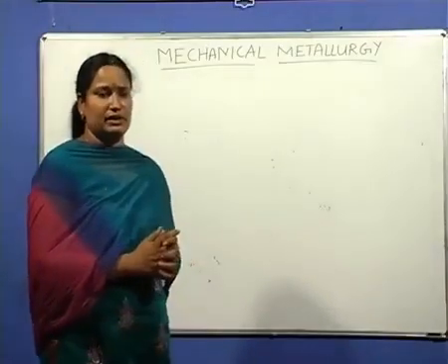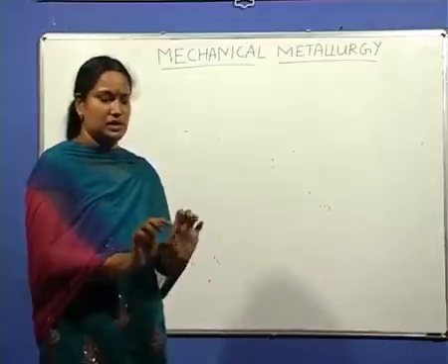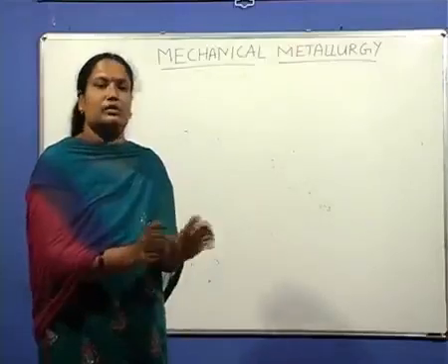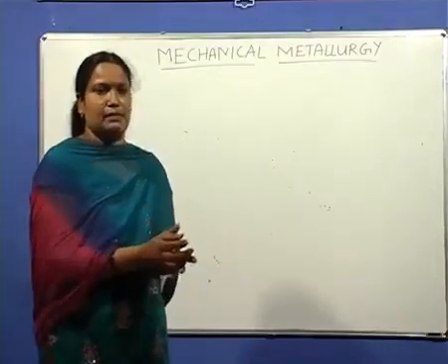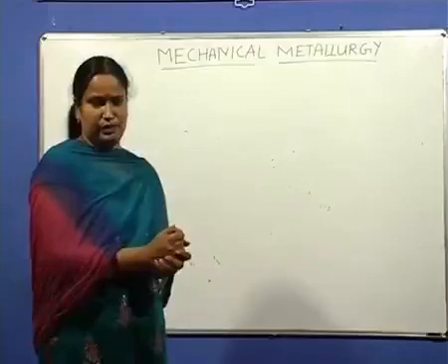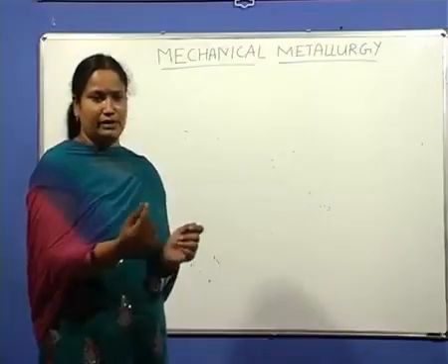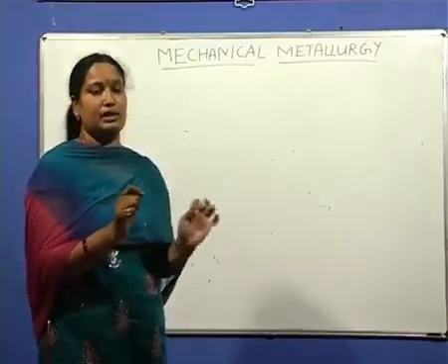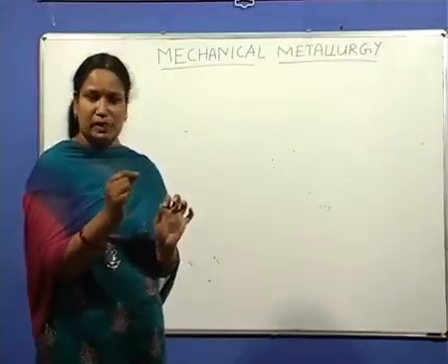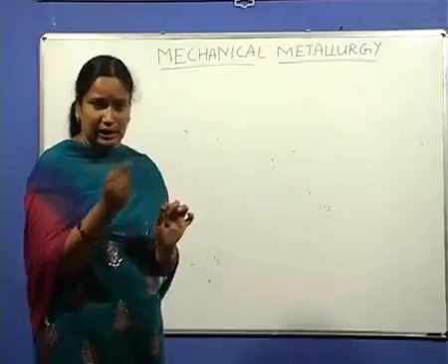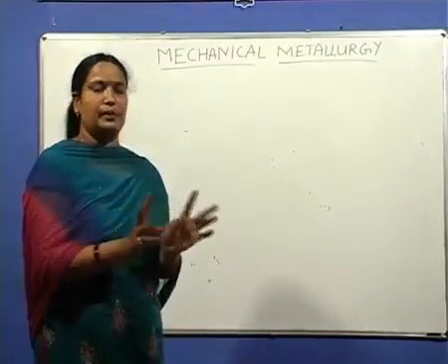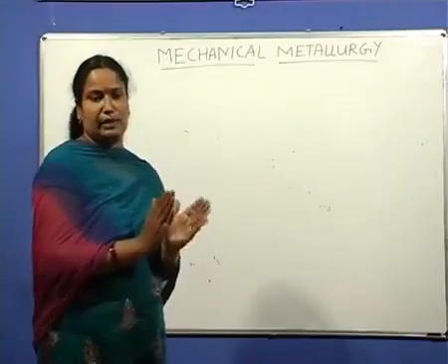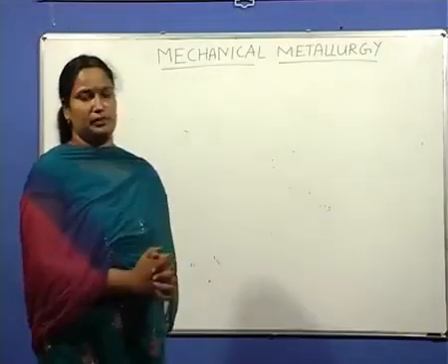An example of a brittle material is a chalk piece. When you apply some stress or force on a chalk piece, it breaks without undergoing any plastic deformation. If you take a small steel wire and try to fracture it, before fracture the material undergoes some amount of plastic deformation, that is, it necks down before it breaks into two pieces.